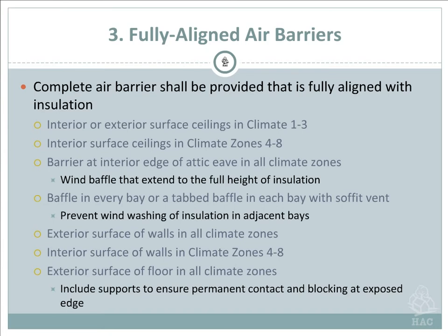And if you're trying to meet just the minimum, it's a lot easier just to go above and beyond by adding a foam board, even if it's a 1-inch foam board on the outside. It's going to give you that little margin that says you exceeded the IECC 2009. So those are some of the things that you want to think about as you're doing this. Again, baffles, very important.